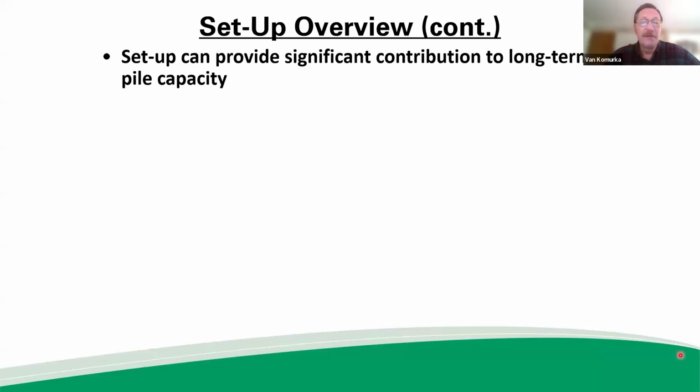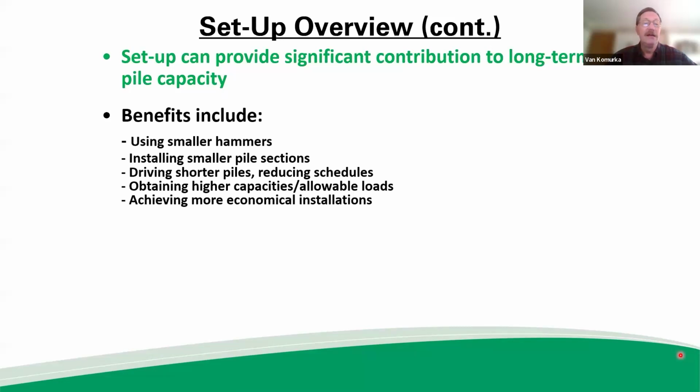We're going to see that setup can contribute a lot to a long-term pile capacity. And that's where the economy comes in. That's where it really shouldn't be ignored and it should be tested for and incorporated in design. So if you characterize setup and incorporate it into design and installation, you can use smaller hammers, you can install smaller pile sections, drive shorter piles, which means a reduced driving schedule, or for a given depth, you can obtain higher capacities and allowable loads.